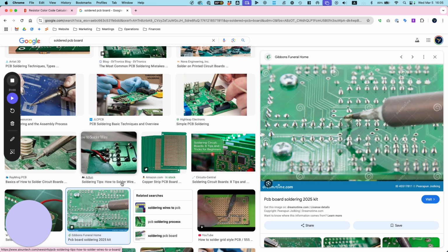More energy in the sense it's more capacity, right? It's like you have 2 sets of batteries. It's like having two tanks in your car. Okay, so you still have the same voltage, but now you have double the capacity. So that's why you'll usually see a parallel circuit on bigger batteries. This is 12S20C, 44.4 volts, 710.